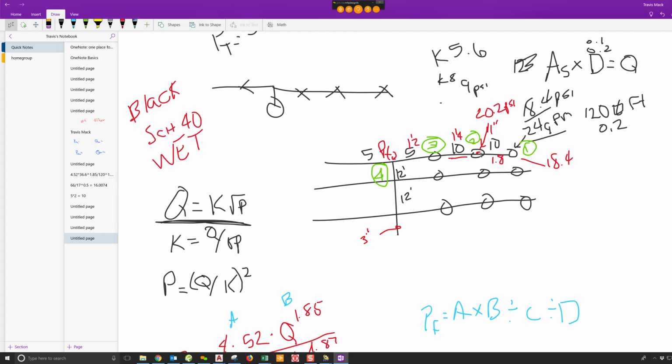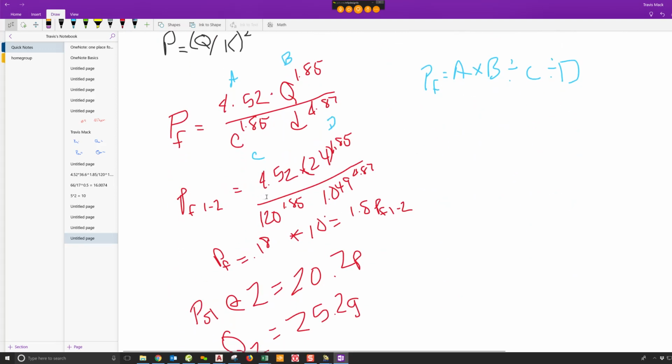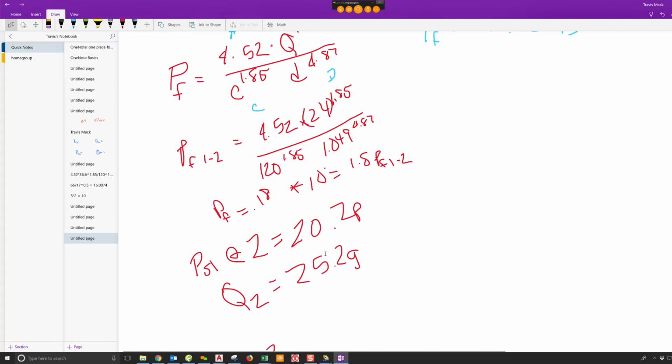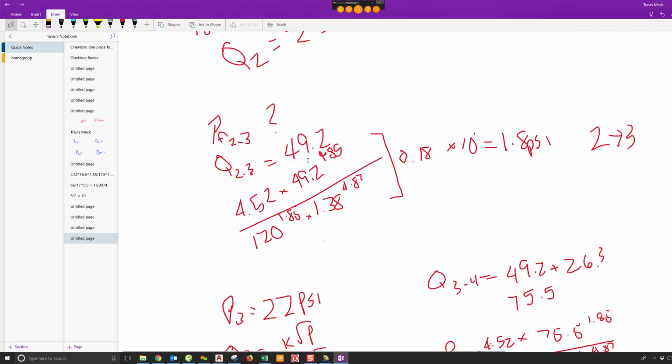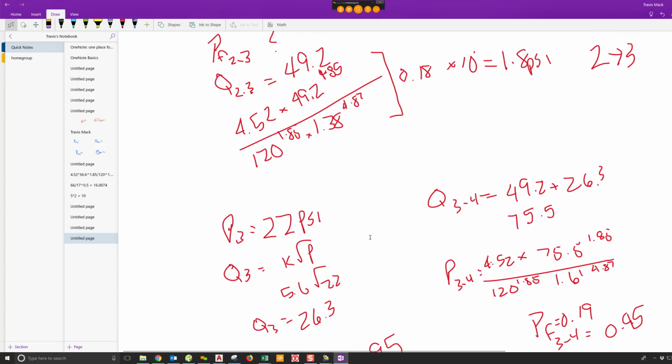Actually, back when I took it, they didn't even have stuff like that. You just need to make sure that whatever flow you come up with coming out of, like, 0.2, satisfies the minimum required. We said each head had a minimum of 24 gallons, and every Q that we developed, 25.2, then there was another individual Q there of 26.3. We were always in excess of 24 gallons.